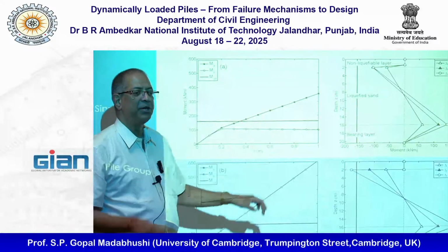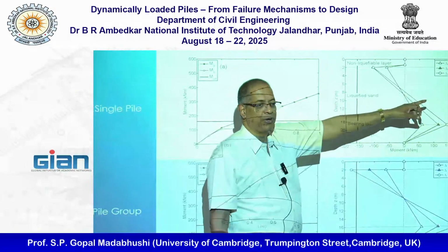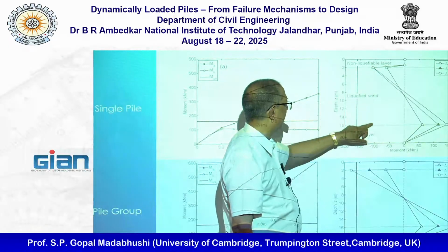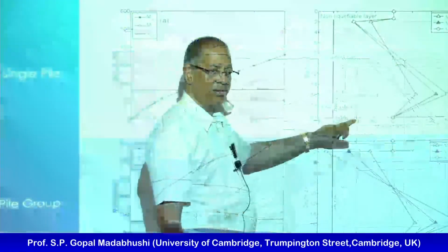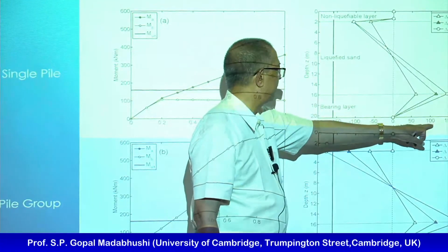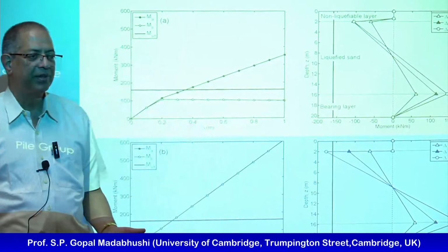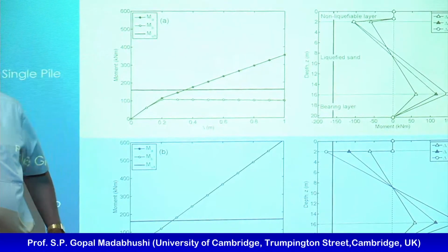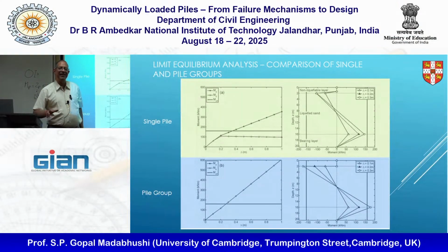It's like this. You go and design so that at the top of the pile, even with 0.3 meters, I get at least a moment capacity greater than 100. And at the bottom, it should be maybe close to 150. And then they can design. Because if you tell them sensible things, structural engineers can handle that. If you say, well, it's all complicated, then they'll run away and never come to see us.